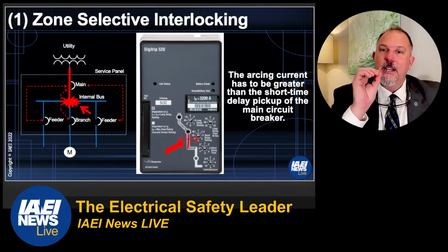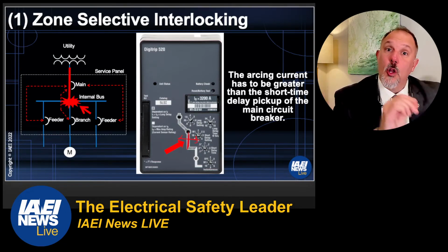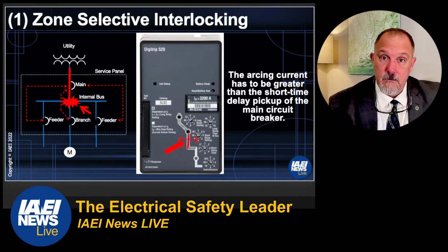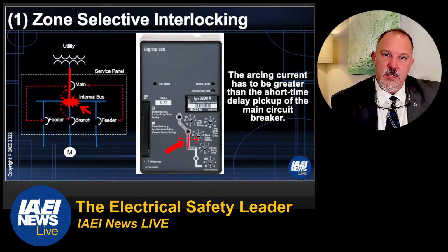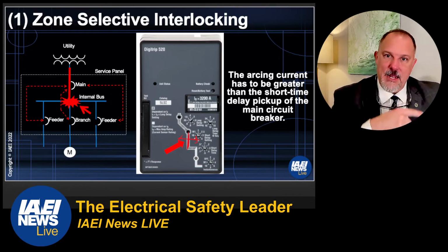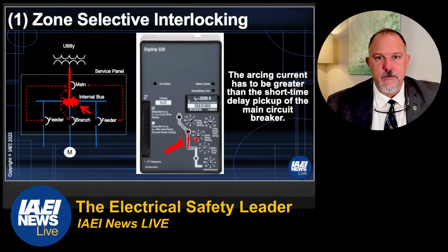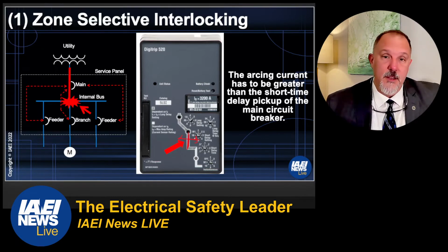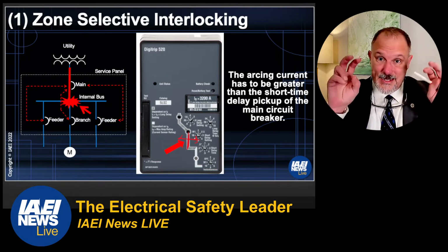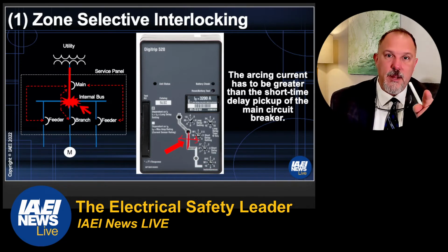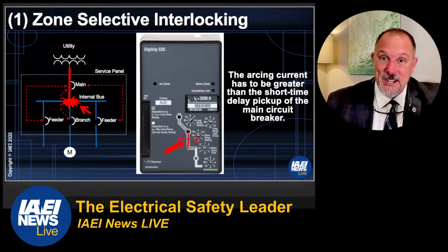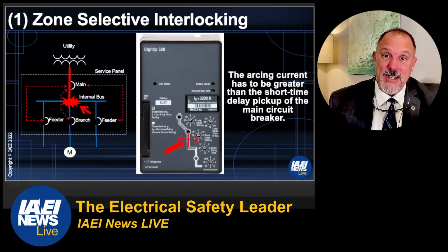It either has the trigger point higher or lower in amps. So the setting of that trip point will help you understand when that signal is being sent to the main overcurrent protective device, who's looking for the signal, the restraining signal, so that it just goes based upon the trip curve that you programmed into it, or maybe didn't program into it, right?